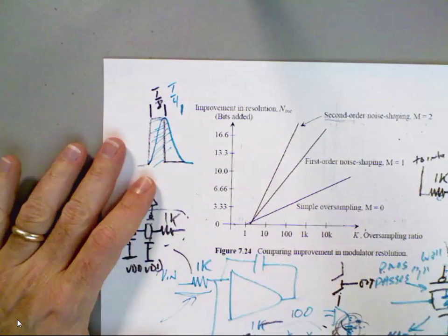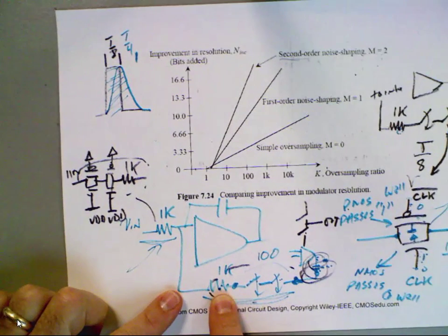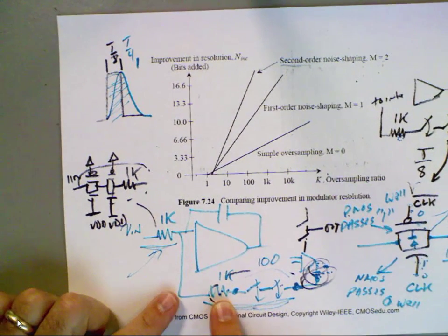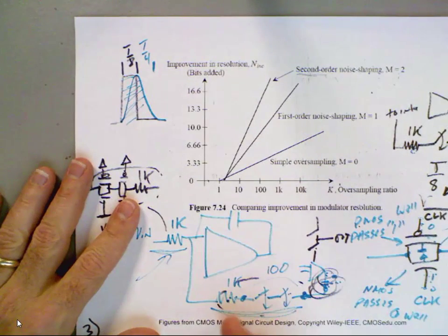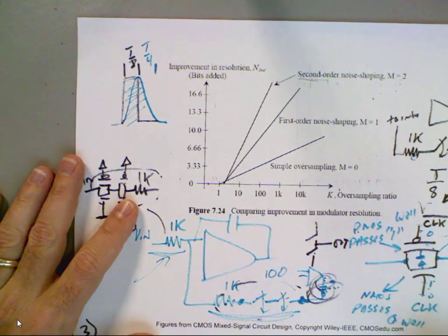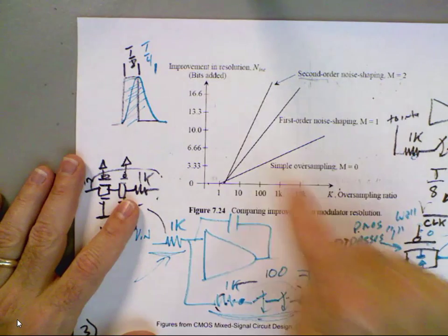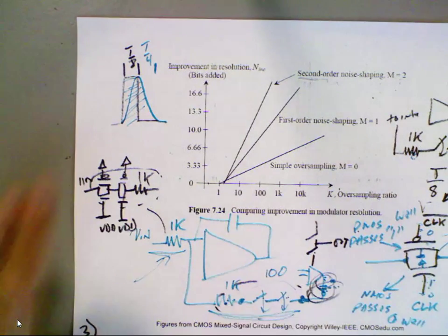You want to turn them on. But if you have the signals here and you look at the charge or the current that flows through the resistor, and you see that it's a small amount of charge, then you know you have to adjust the clock so they can turn on and put back a more reasonable amount. Because everything has got delays in the feedback and turning these on. Remember, there's a process characteristic time constant that says I can't turn this device on any faster than this, whatever it is, and it might be 100 picoseconds in this process, so you're dealing with that.